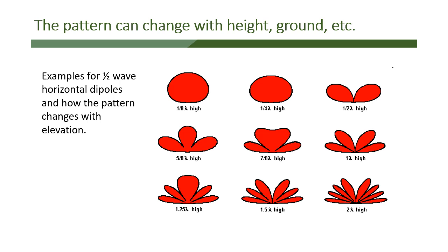When you have a side lobe like that, it means the energy is going up into the ionosphere and almost straight down, which is good for local communication. And we have two lobes that are good for distance communication. So as you can see, the patterns change as we raise this antenna higher and higher. This one's specifically for HF, but you'll have some similar effects for VHF.